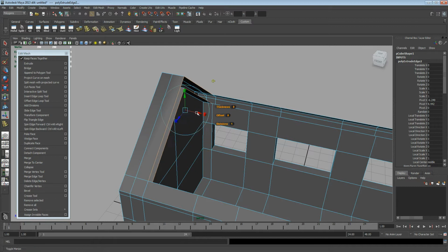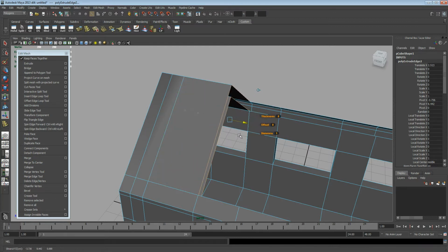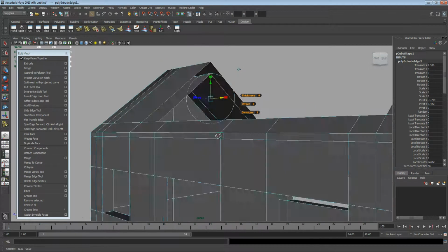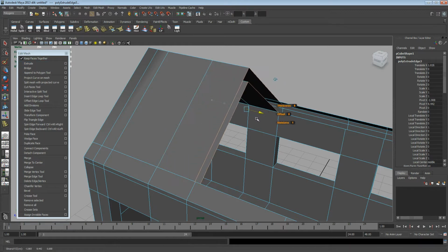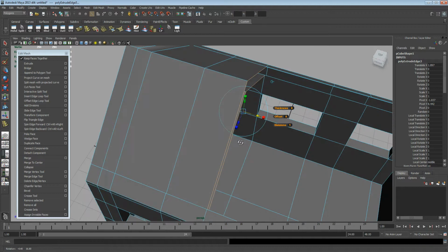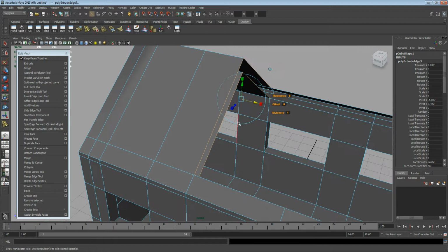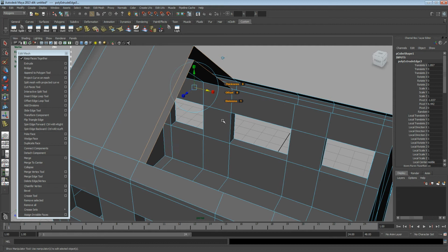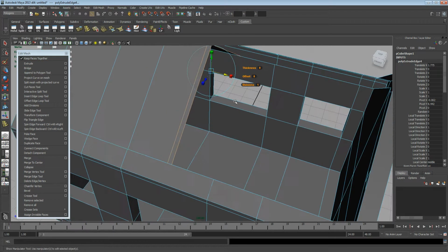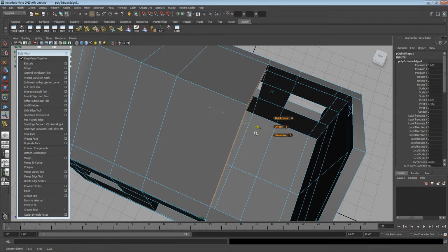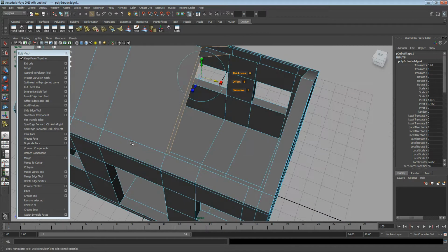So what I really need to do is to make sure that I extrude this across carefully. And again, please remember, whenever you extrude, please extrude it outwards so that you can see that there's a thickness, because I have seen a lot of students extrude twice without knowing and create problems in their geometry at a later stage. So extrude and move it close to where the edges are.